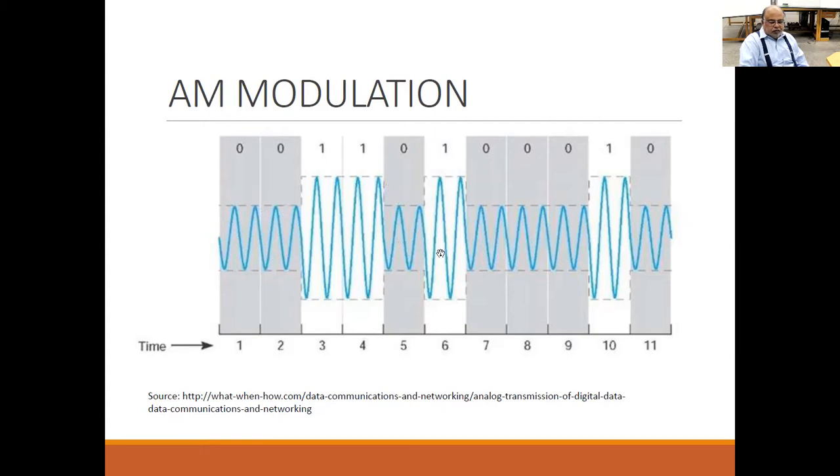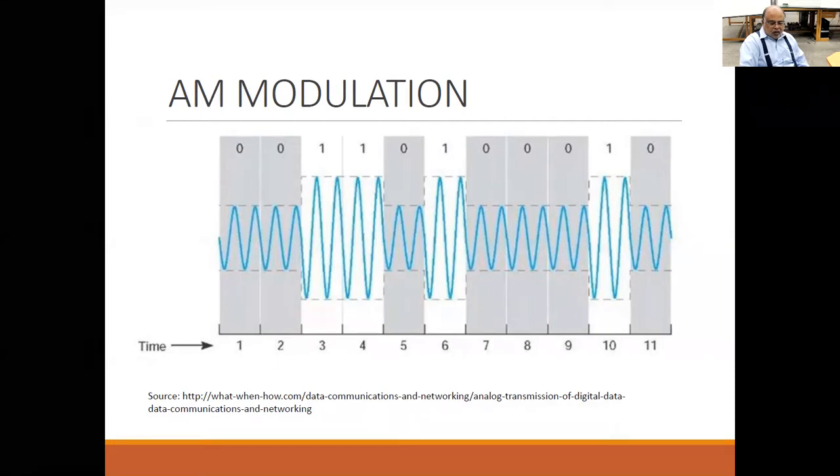And the advantage of amplitude was that it could be easily decoded using a simple peak detector that you probably study in your circuit devices course or something like that. So by simply using a diode and a capacitor, you could get the AM unmodulated signal at the output using a peak detector. So this was the AM modulation.